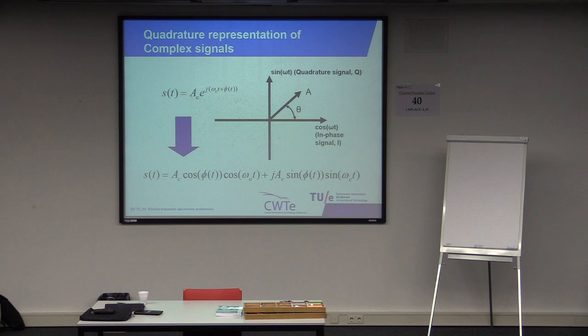Then Q decreases and I increases. So I'm going this direction, and I get this circle, so my amplitude phase vector turns around in this direction, and this means I have a negative frequency. If I had a positive frequency, then positive frequencies by definition are purple, because that's the color that I have here, and it would be like this.